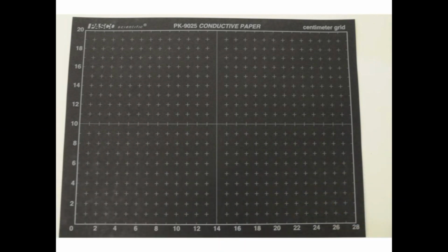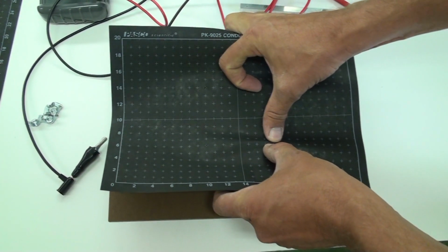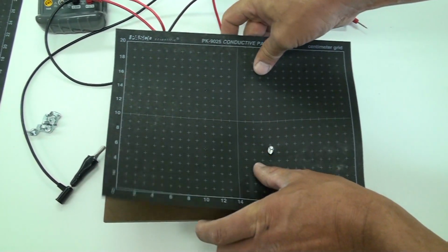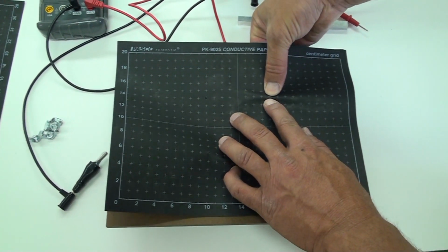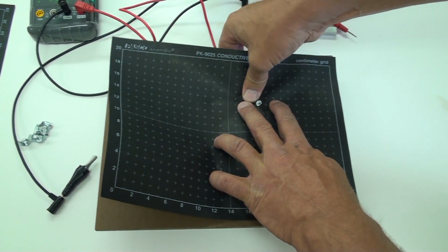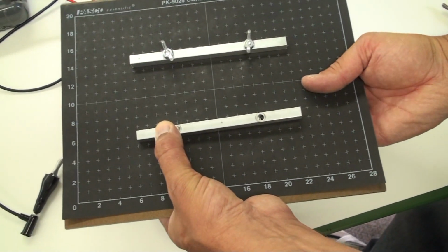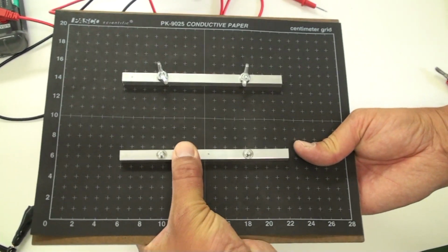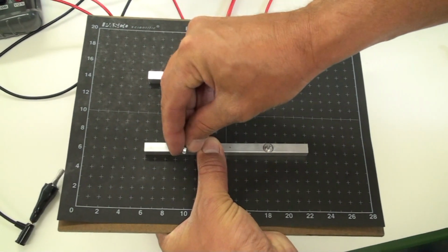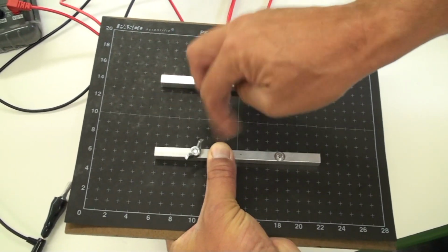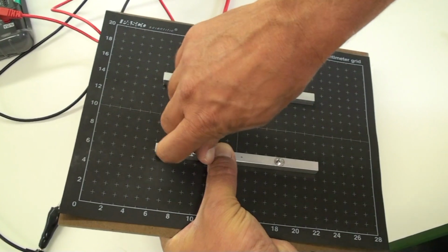If you consider the marks on the paper like XY coordinates, the holes are placed at the points 4, 4, 4, minus 4, minus 4, 4, and minus 4, minus 4. After making small starter holes at each of the 4 points, carefully push the screws through each hole in the paper. Place the connecting bars in contact with the paper and use the wing nuts to make the contact solid. As you'll see, we neglected to screw one of the nuts tight enough when we were constructing ours, and this